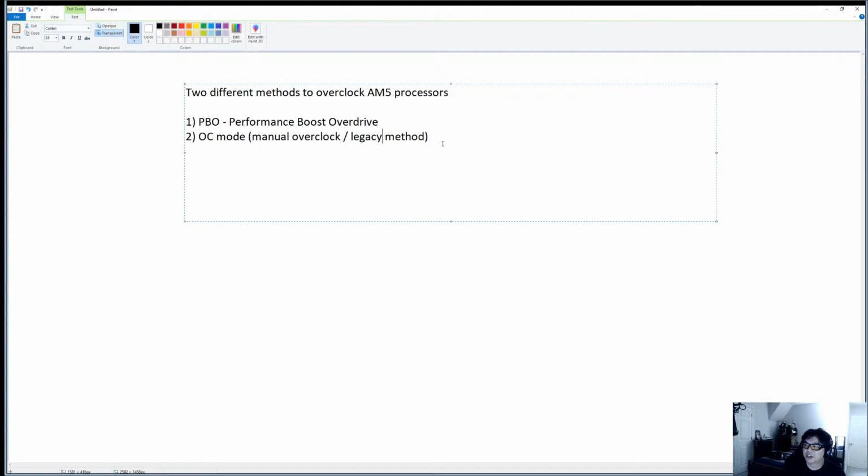So in the end, a lot of the overclocking has to be done using PBO, because you do want to get the benefit of the lower idle power states, the lower C states. The efficiency gains with Zen 4 really only make PBO the realistic method for overclocking.